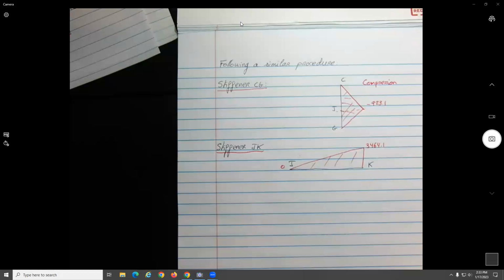Yes. So that's what I'm saying. Sometimes you can have a problem which is statically indeterminate, but you can solve it as statically determinate, making the assumption that if it is safe solved as statically determinate, it is going to be safe with the extra members.